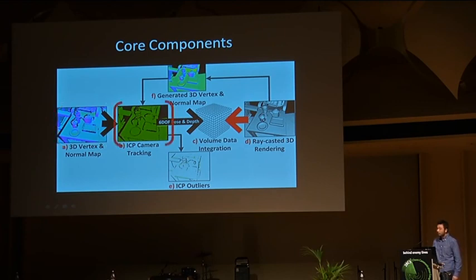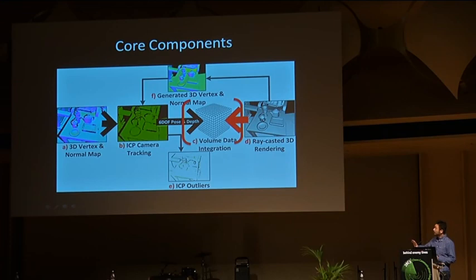And then based on the point clouds of the current image frame and the previous image frame, we compare the relative spatial offset between the frames. And then once we know the 6 degrees of freedom orientation of the camera, we can actually integrate the depth data in a global volumetric data structure. So this data structure doesn't only contain the 3D point cloud of my current view, but it stores, memorizes all the scenes it has seen previously.